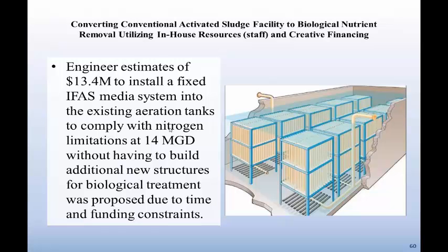And this would actually bring us up to 14 MGD. Remember, we went from 18 to 13.8. With the recommended IFAS, we would have only crept back up to 14 MGD. And the recommendation was made because by installing the IFAS system, we would not have to build additional new structures for biological treatment, and also due to funding constraints.